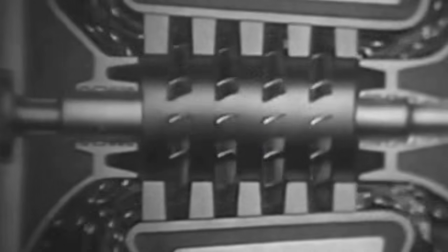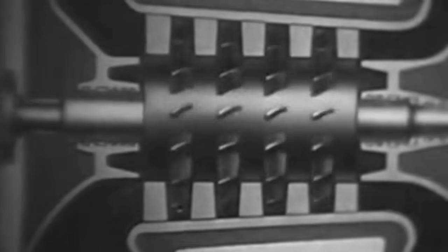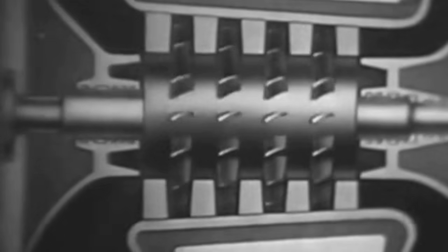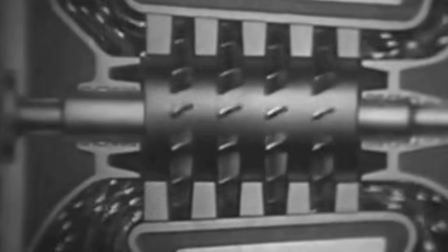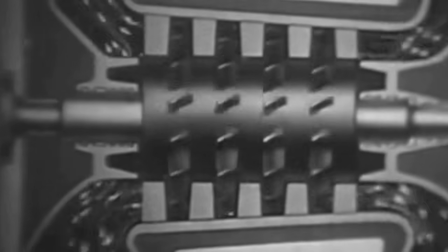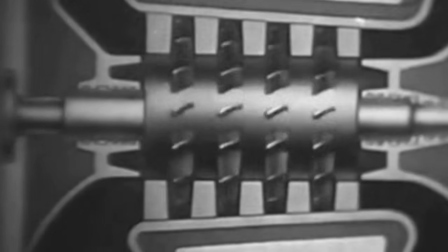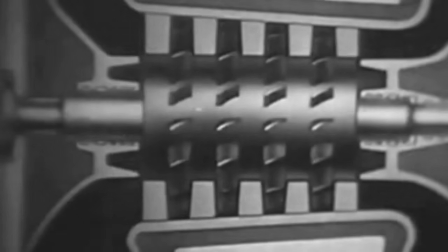Another important point: because a large amount of scavenging air was injected into the gas generator cylinder during scavenging, its exhaust temperature was slightly lower, and the gas temperature before the turbine was relatively low, approximately 1,100 degrees Fahrenheit, as opposed to the 1,650 degrees Fahrenheit found in conventional gas turbine engines. This allowed for a simpler turbine design, using inexpensive heat-resistant steels rather than specialized alloys. This reduced cost and increased reliability and durability.